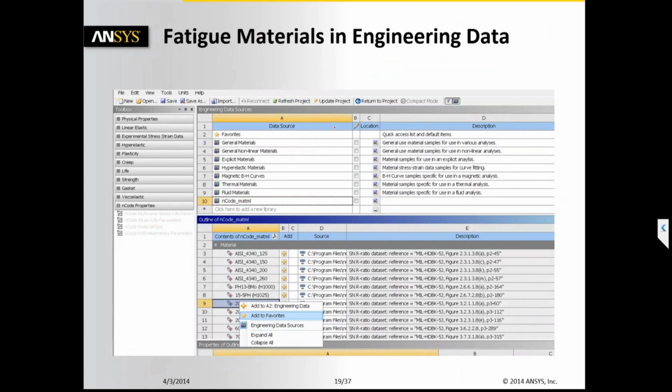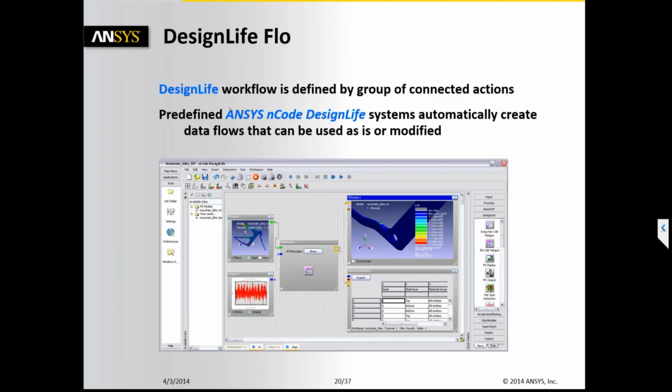There are two sets of databases we will be seeing in ANSYS Workbench. One is the standard material database, which you typically get from the ANSYS Engineering Data. There is another database that can come from Granta. Granta is a material database, and when you install the nCode part, nCode also gives you a material database with very detailed fatigue properties for the given material. Then once we bring the model, I think we will just get into the model.